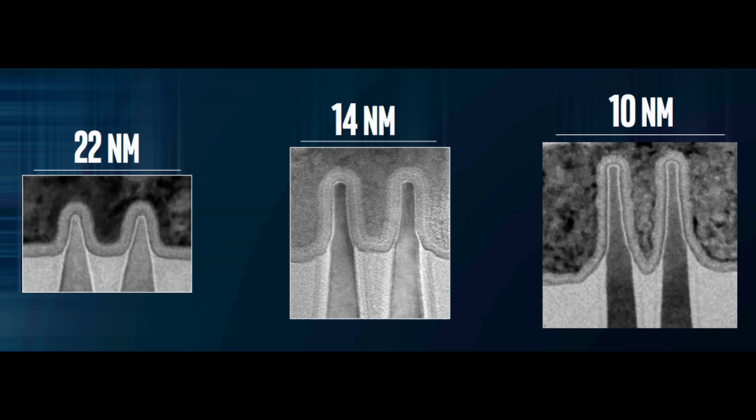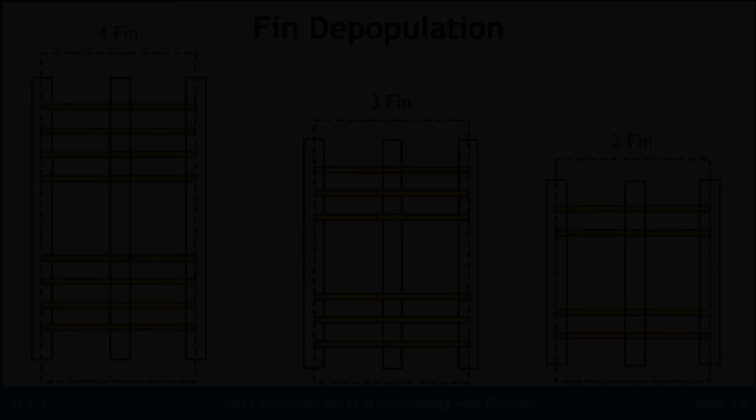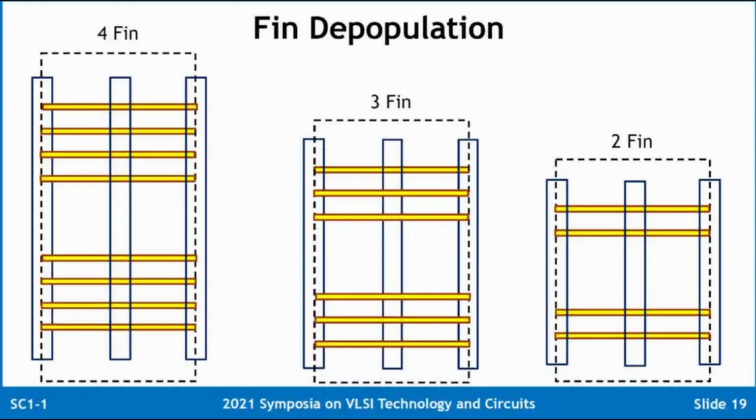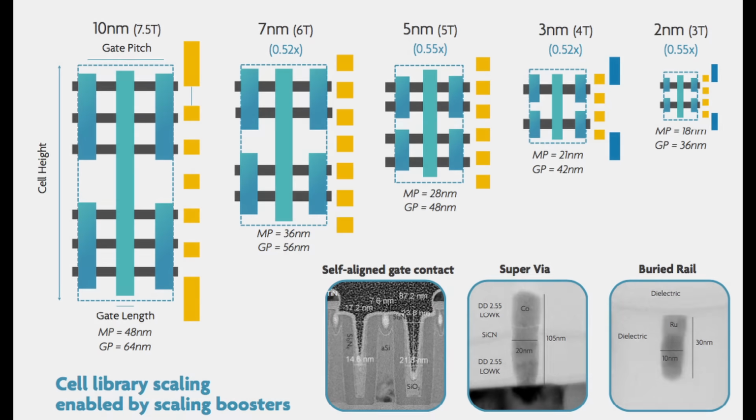It's possible that a 3-fin transistor based on Intel 4 could offer a better performance than a 4-fin Intel 7 transistor, if the increased fin height adds more conductive strength than what is lost by removing one fin. This example is based on an Intel node, but it's the same for all other process nodes, no matter if TSMC, Samsung, or any other FinFET design.